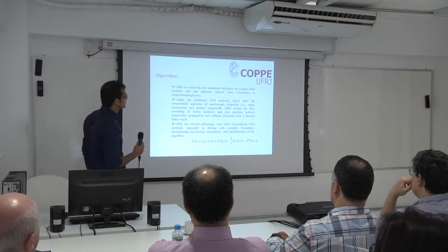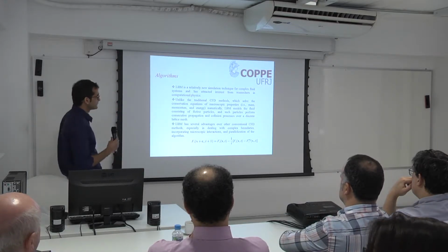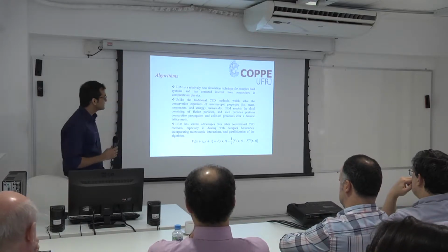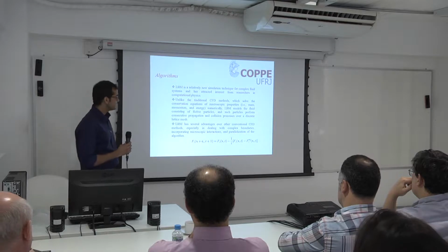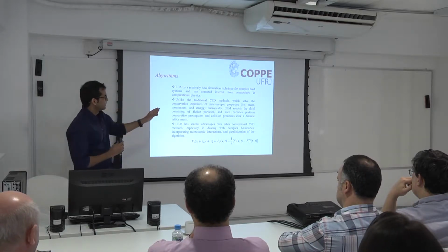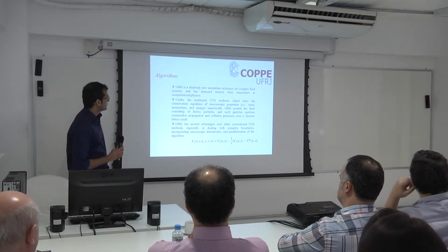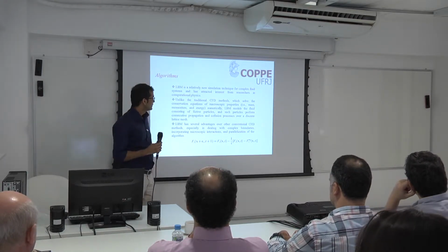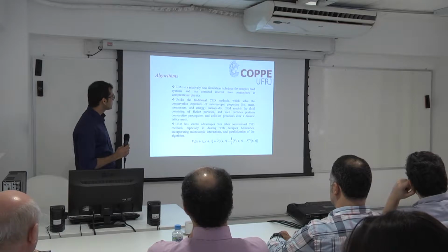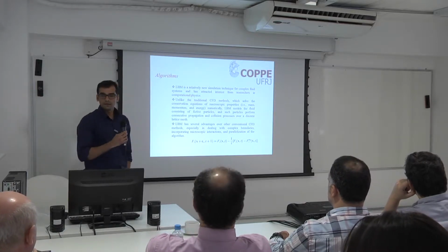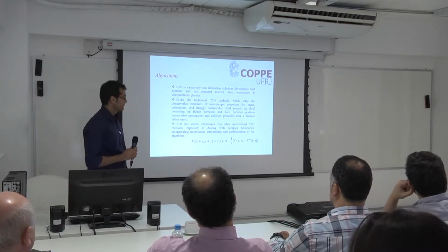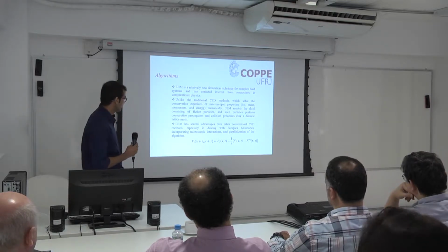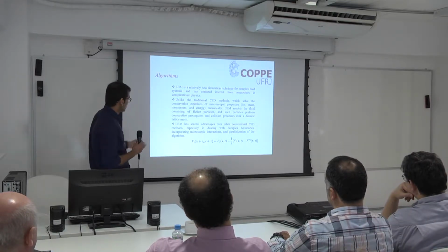Unlike the traditional computational fluid dynamics methods, which solve the conservation equations of macroscopic properties like mass, momentum, and energy, lattice-Boltzmann models the fluid as consisting of fictive particles, as I said in the beginning, and such particles perform consecutive propagation through the distribution functions, equilibrium or non-equilibrium, which I will throw some light on later.